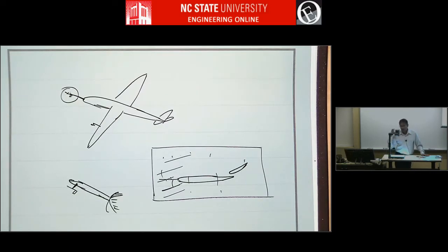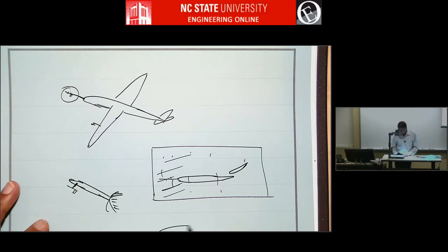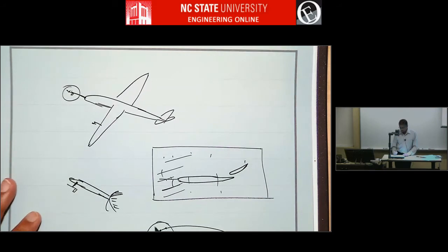No, my PhD student Aditya Saini has actually come up with a way to use 5 pressure taps. He's just finished his PhD, and with these 5 pressure taps, we have tried it. It's working pretty well, as long as it's before stall. By knowing these 5 pressure taps, we have come up with an algorithm to say this is the angle of attack for the airfoil.